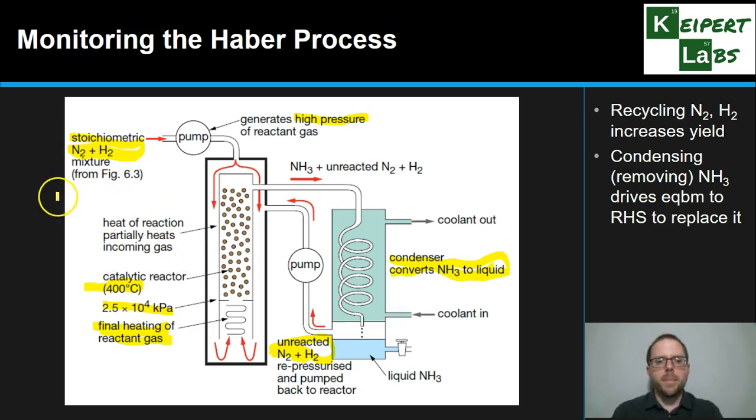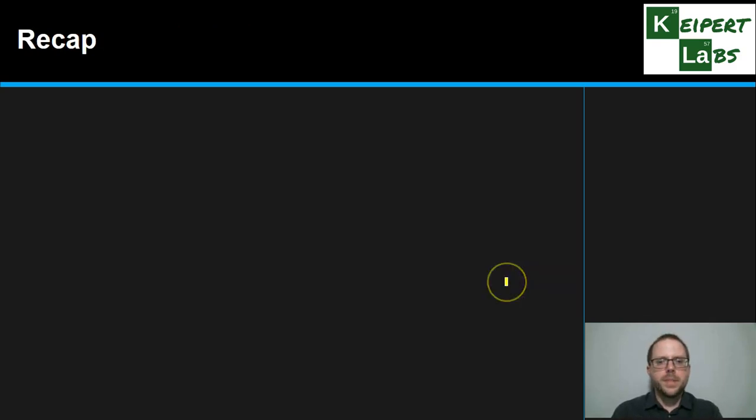So making sure that our gas has no oxygen present before it reaches anywhere near here is really important. Then we monitor the pressure and the composition of everything feeding back into this process, monitoring the ammonia produced to check that it's not contaminated, as well as the gases that are pumped back in. And the pump, aside from getting the gases where they need to be, also helps to maintain the right pressure.